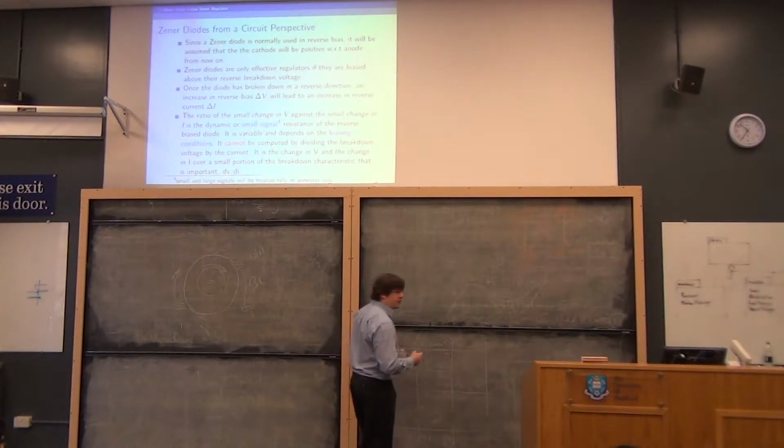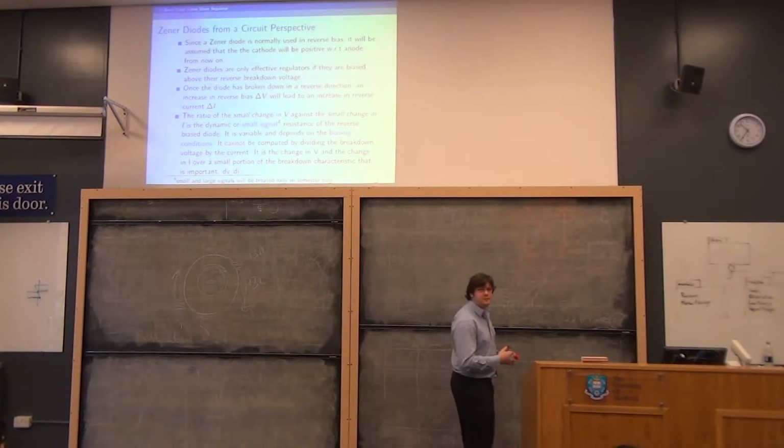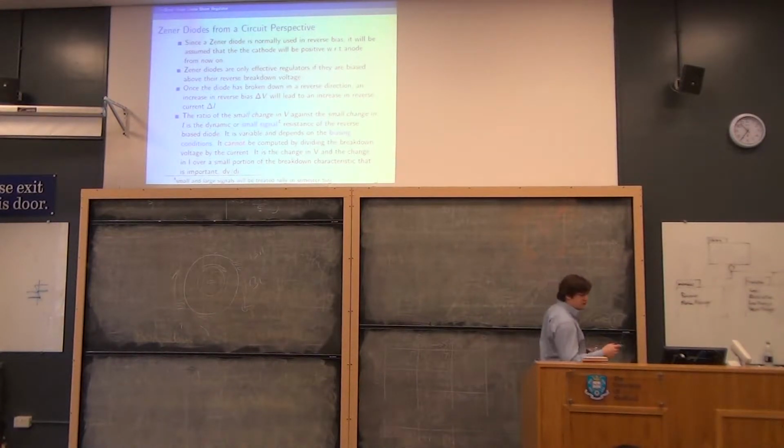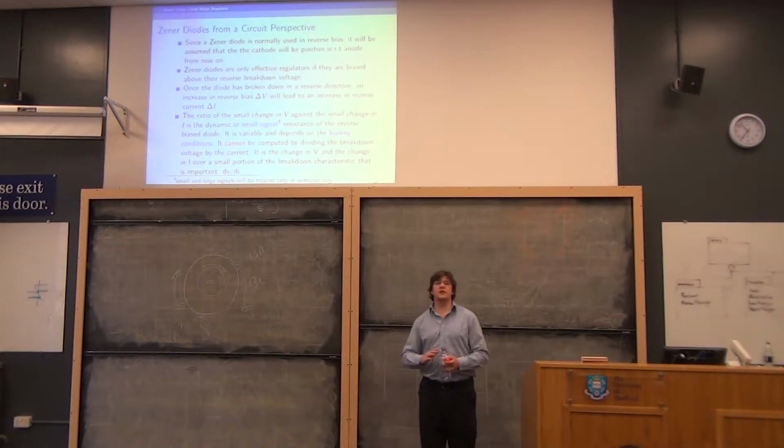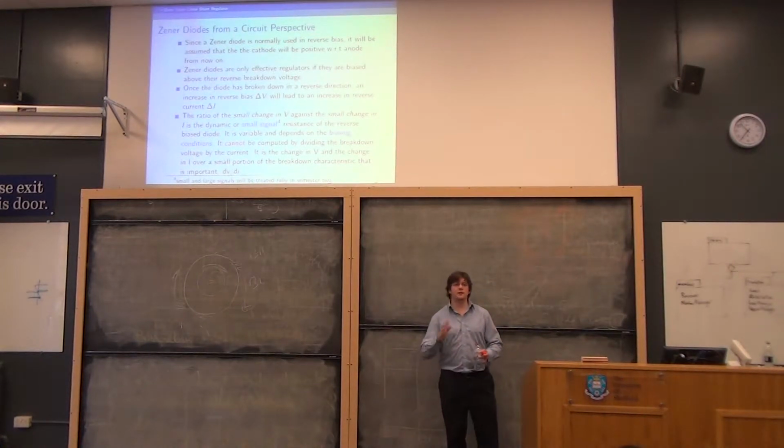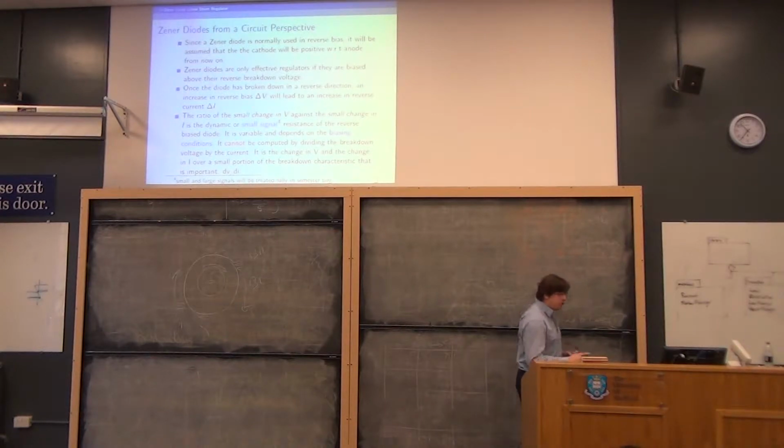But you can't work it out by saying, oh, it's the current divided by the voltage. Not as in, I'll worry about the current with respect to 0, and then I'll worry about the voltage with respect to 0, and then I'll divide one by the other and use Ohm's law. That will not give you the small signal resistance, it will give you something else. We will come on to how you work it out in a bit.